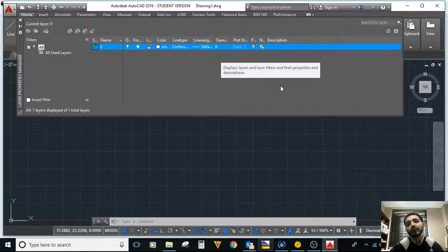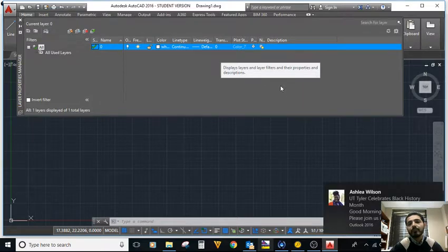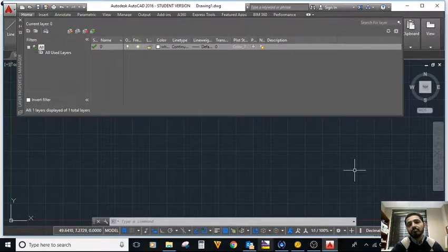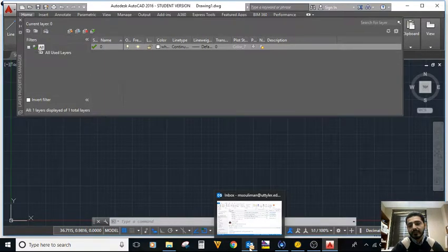If you were to draw the full drawing using one single layer, you've got to go back and forth to change the line style and the color and the thickness every time you want to shift gears from one line to the other. While if you are using layers, that's not the case. You would define the line properties, the colors, everything basically, and it will be easy to go back and forth between different layers.